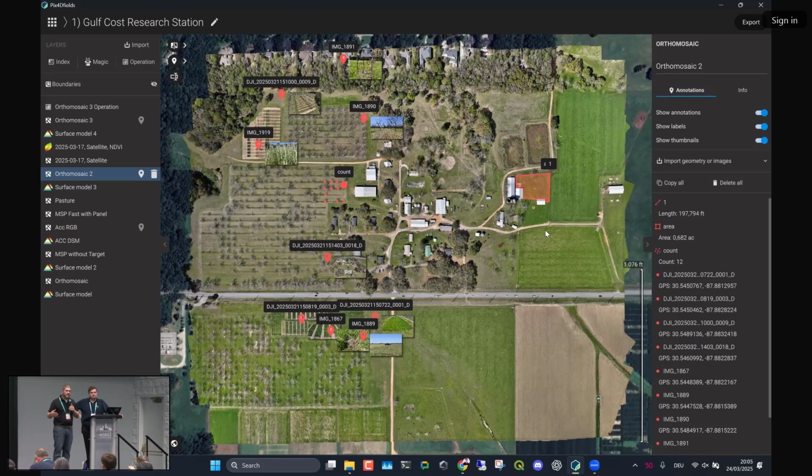I'm not going to encourage everybody to do this. I would just prefer that you use RTK systems because they're consistent and repeatable. But I know in areas where you don't have internet, where it's hard to get internet, you don't have Starlink or something like that, that's where you're going to have those problems, and you're going to have to do offset corrections. You can do them, but we're not going to cover that in this short little course.